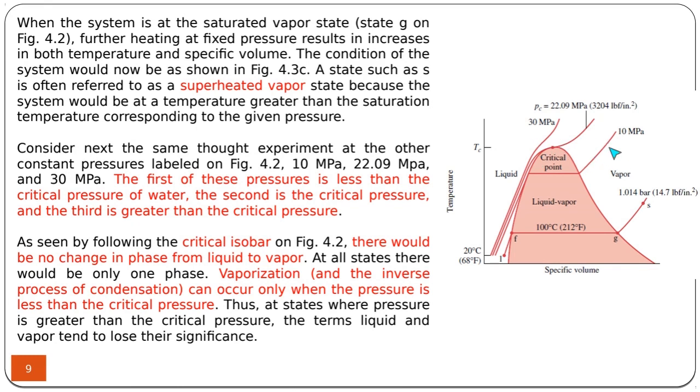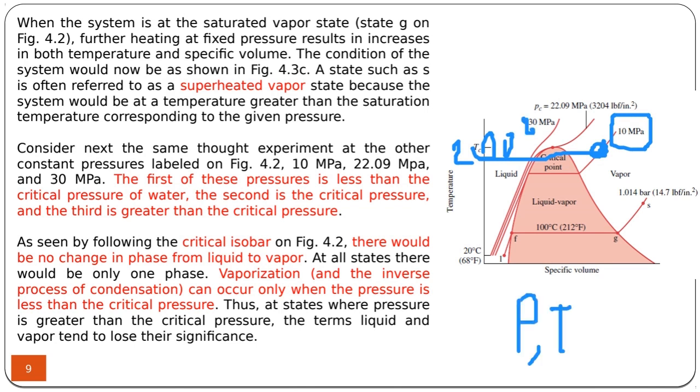So in order to find, for instance, the properties of the vapor or the steam at 10 bars and so many degrees, we don't know, let's say 200 degrees, you need to have both pressure and temperature at the same time so that you can find the specific volume, the internal energy, the enthalpy, and entropy. So this is how you use the superheat table.